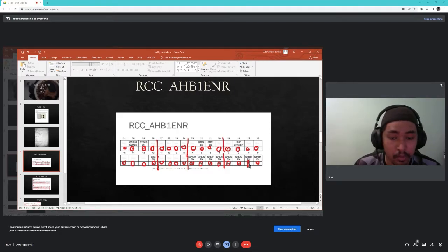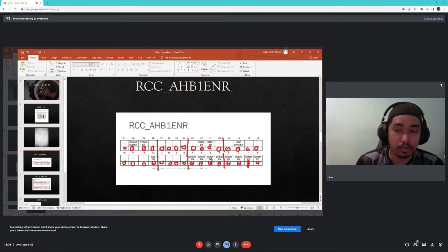So we need to put 1 on GPIOB, and for the rest we need to do the masking, which is to put 0. So we have zeros all the way, and at GPIOB we need to put 1, so 1, 0.